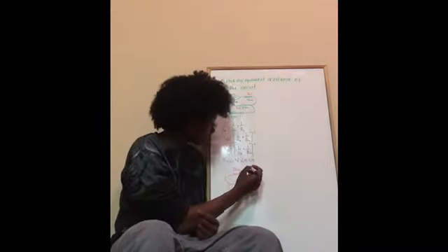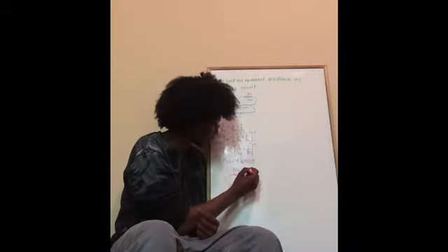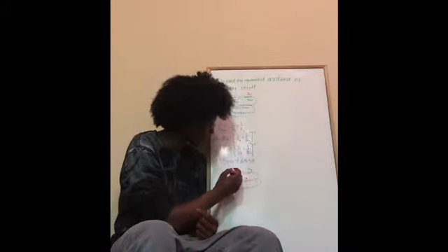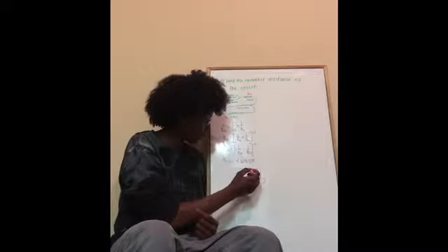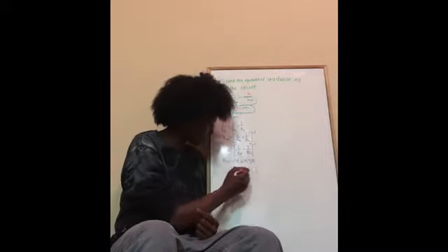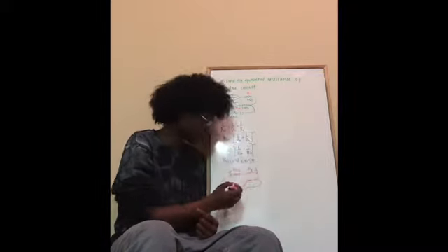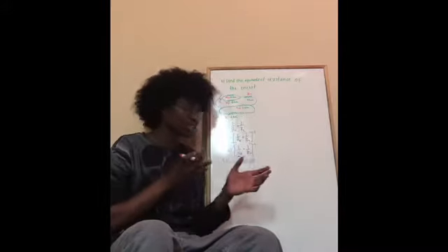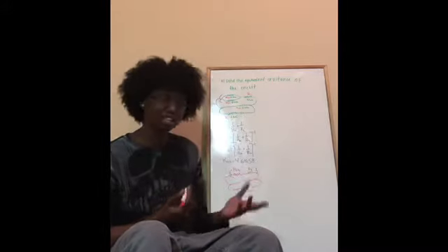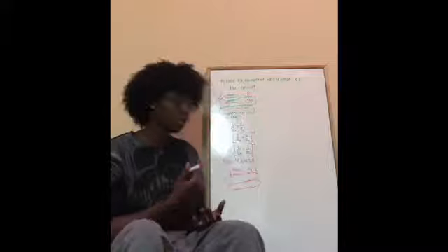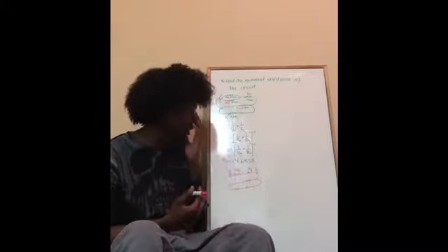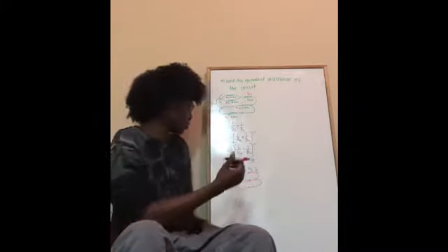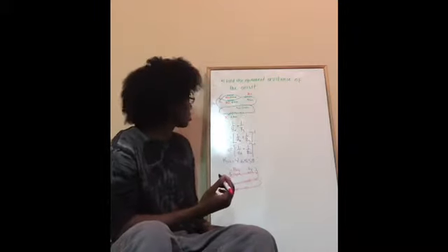Now we're actually going to combine our R4, which is here, with our R23. So these two right here are sitting across each other on the same path. So they're actually going to be in series. So I'm going to actually use a series equation now to solve for R23 and R4. So please excuse me.